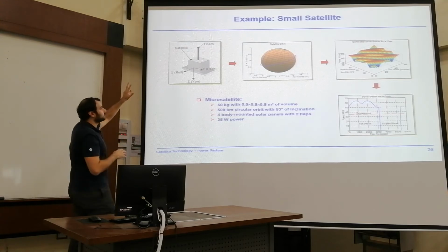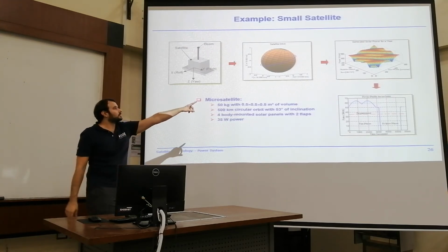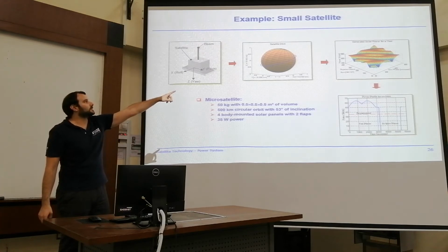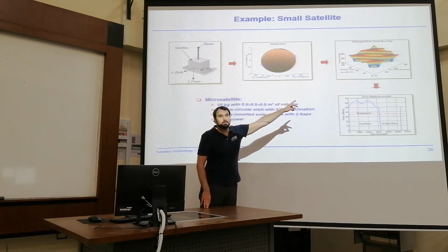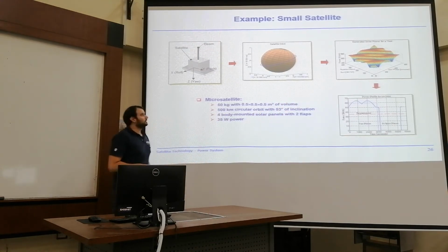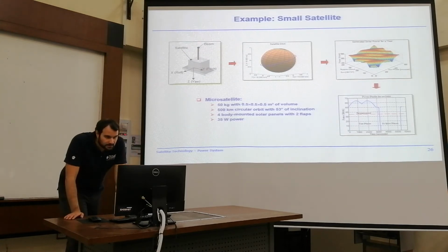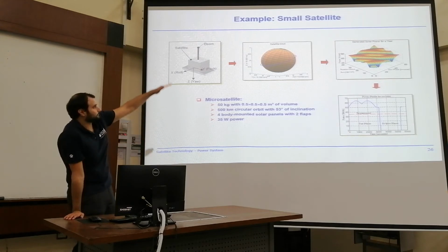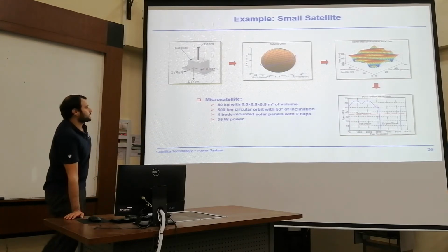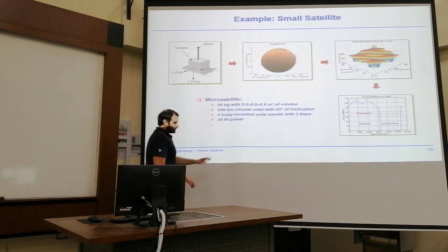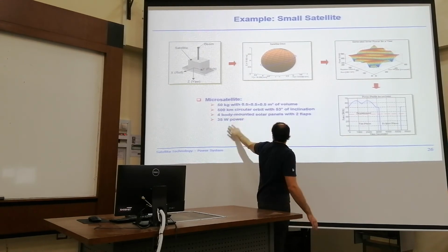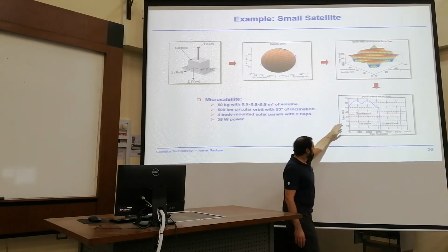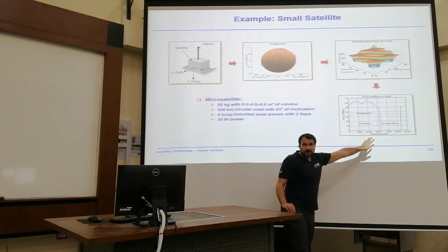With the satellite orbit and your design, you can have a graph and check the generated solar power for one year. And you see, this is anything but linear. It's fluctuating over the year in many dimensions, not just for the sun phase, but also for the rotation and the total power output. And you can see down here on the lower right plot, our required power is about 35 watts. And we have the sun phase and the eclipse phase.